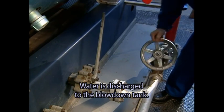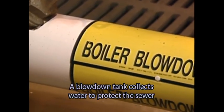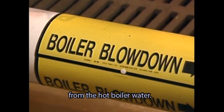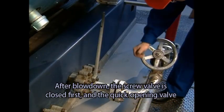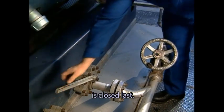Water is discharged to the blowdown tank. A blowdown tank collects water to protect the sewer from the hot boiler water. After blowdown, the screw valve is closed first and the quick opening valve is closed last.